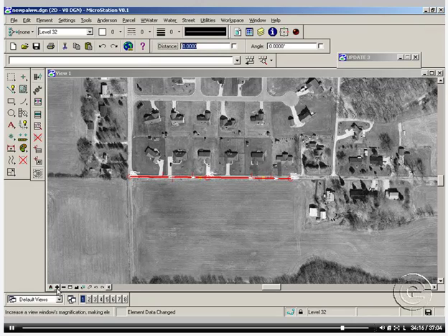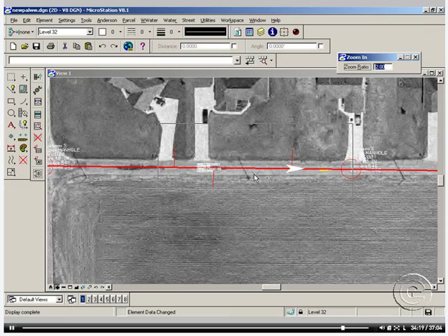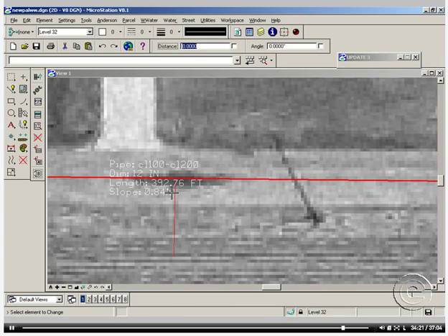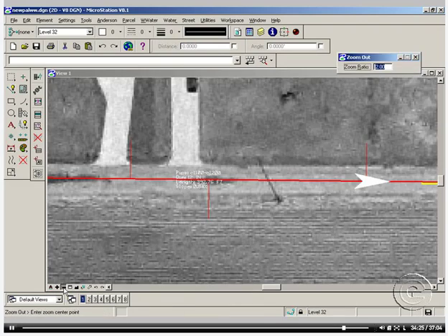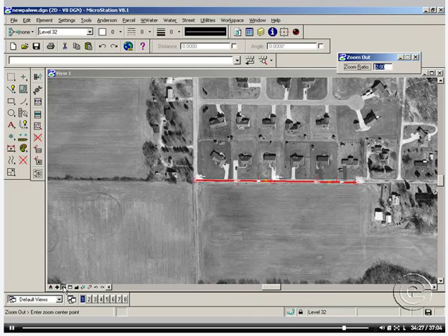update. Again, as you go to your map and zoom in and look at the information, you would see that your slope has been changed for that pipe due to the new invert elevation that you put in. And you could do the same thing also for the other pipe.